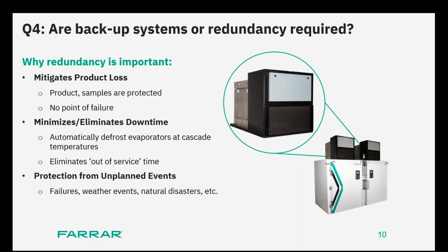If you do not have mechanical redundancy, someday you will have an alarm, and most likely it's going to be a high temperature alarm. When that alarm occurs, the fire drill will happen because now you have to rush to save your product. And in rushing to save your product, you could lose some, might not, and your system could be down for a long time before whatever has occurred has to be replaced.